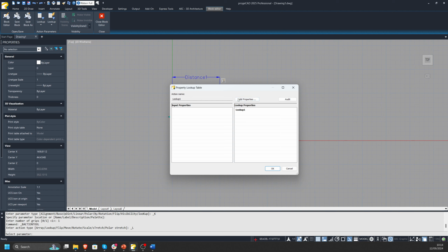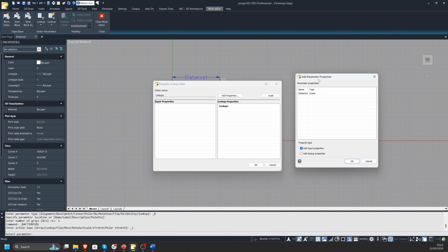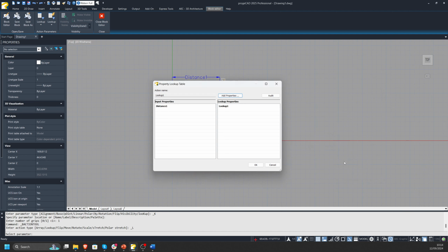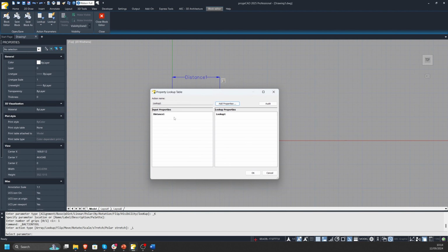Now here we can add properties that we already have on this element behind us. Let's add the distance parameter that we just played with, and underneath it you can write down all the increments, or just basically like the list parameter, but it will do it a little bit different. I will show you. We can write down 100, 125, let's do 200, and on this side you can also write down a different name, like small for small table, medium table, and large table.